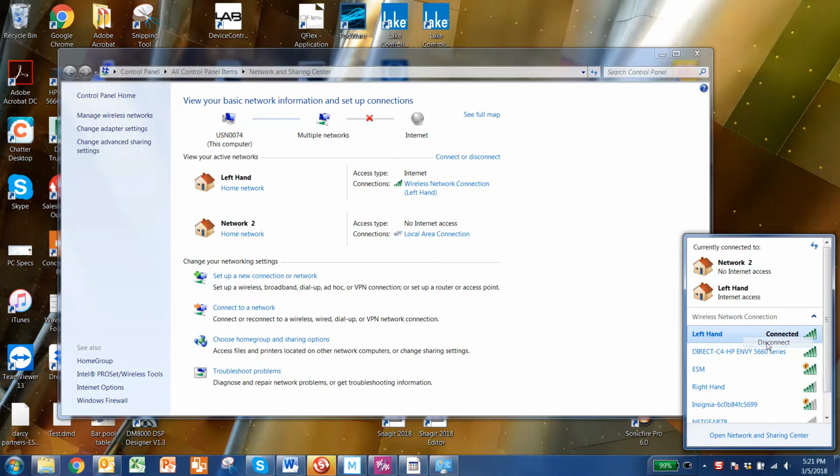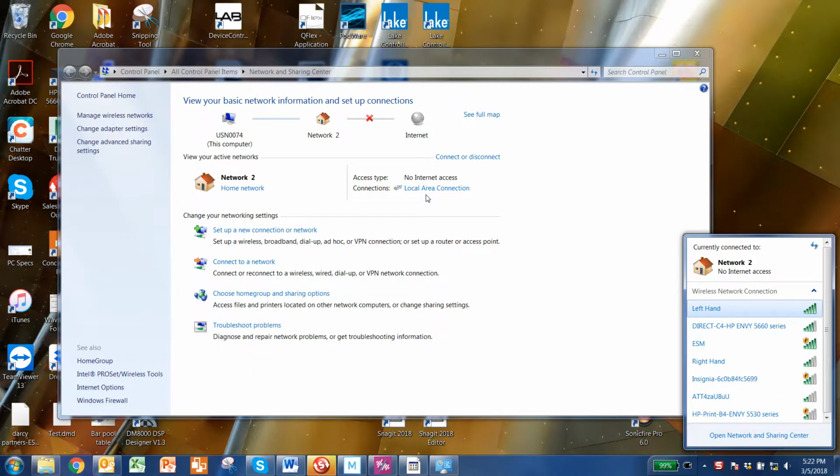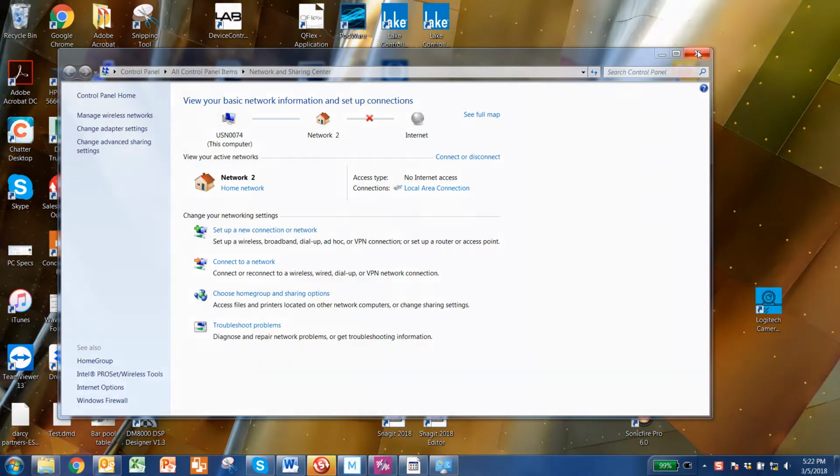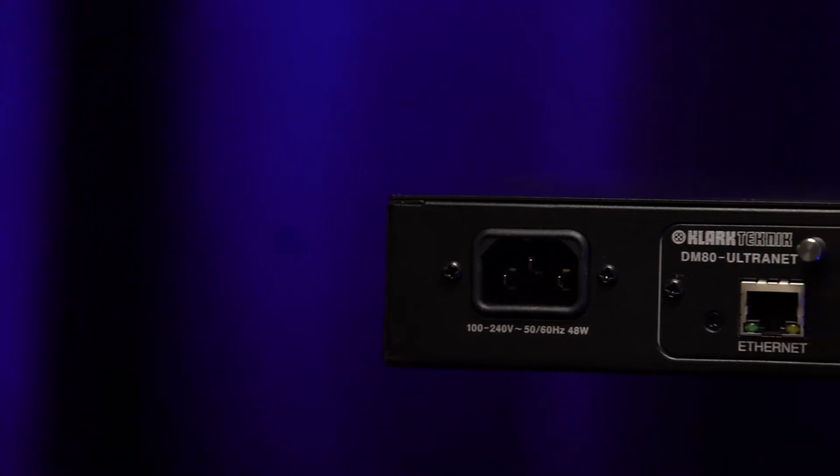Communications to the DM8000 is established through the Ethernet port, which is located on the back of the DM8000. Be sure that you are plugged into the Ethernet port and not the Ultranet ports. You can use any type of standard Ethernet cable to establish direct connection between the PC and the DSP, and the DM8000 also ships with a standard Ethernet cable.